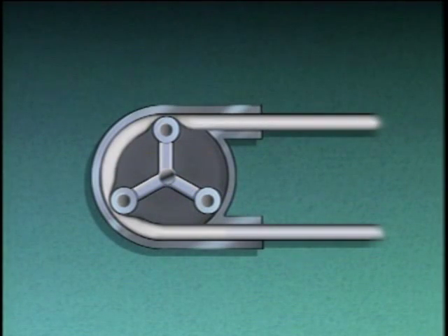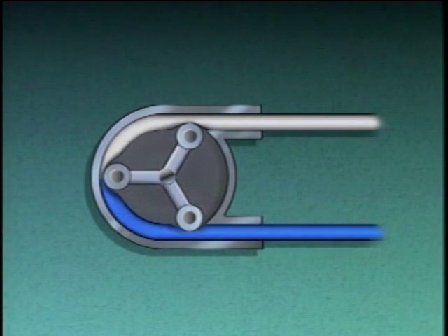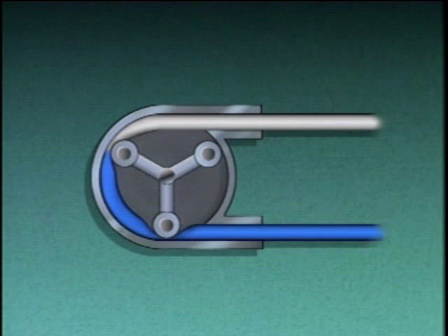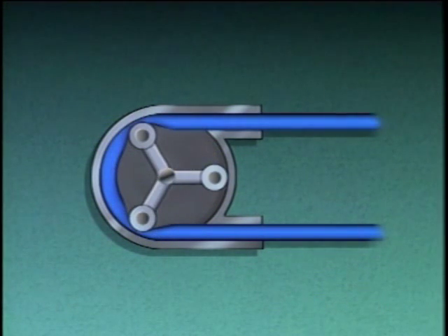During operation, liquid is drawn into the tubing at the suction of the pump. The rollers turn with the rotor and compress the tubing, trapping liquid inside. As the rotor continues to turn, the rollers force the trapped liquid through the tubing and out the pump's discharge.